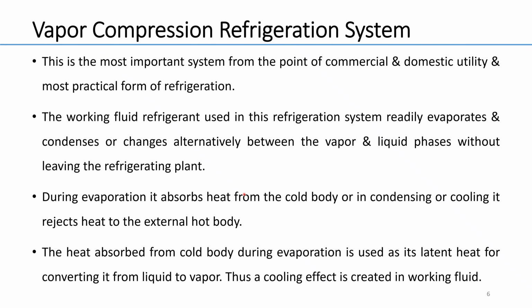During evaporation, it absorbs heat from the body, and during condensing or cooling, it rejects heat to the external hot body. The heat absorbed from the cold body during evaporation is used as latent heat for converting it from liquid to vapor. Thus a cooling effect is created in the working fluid.